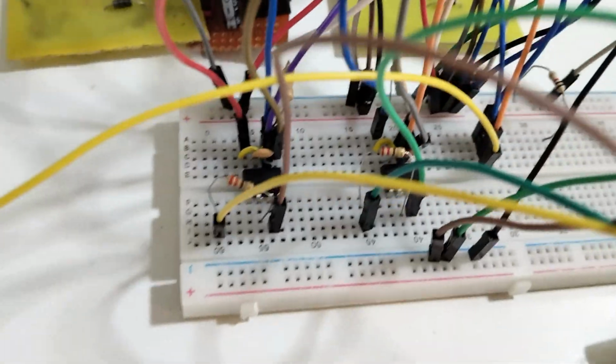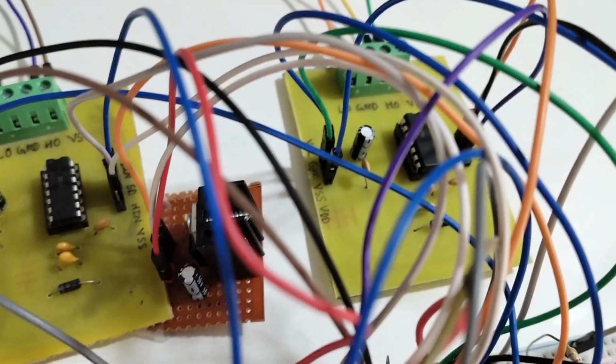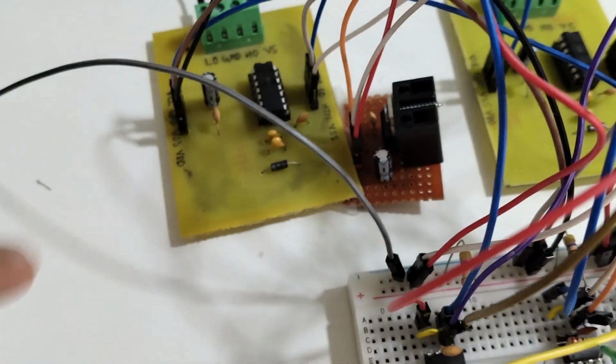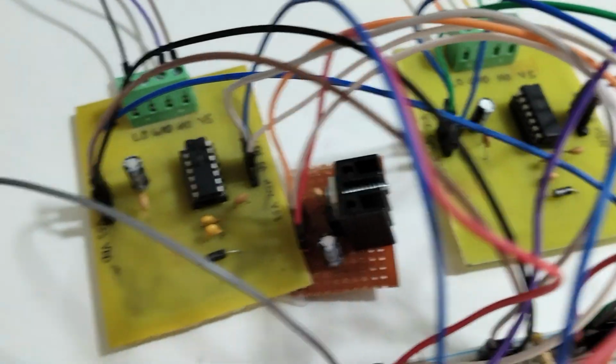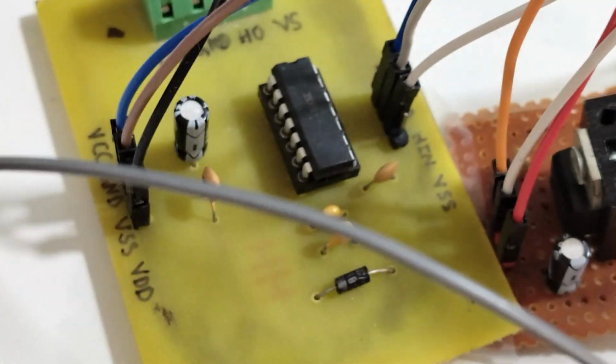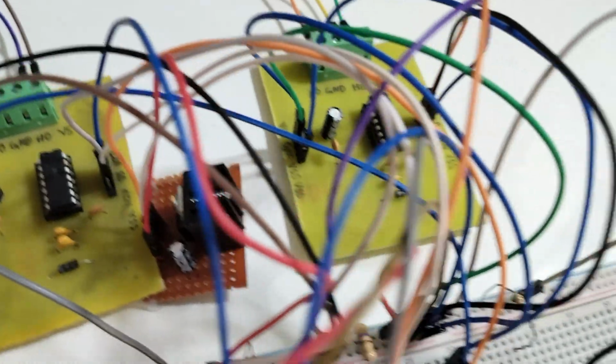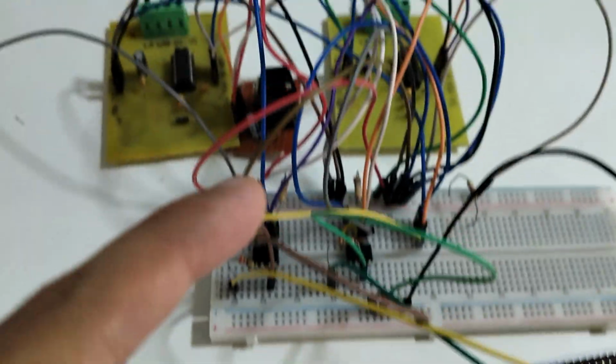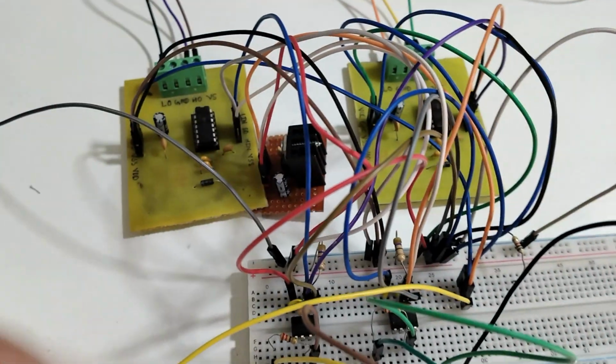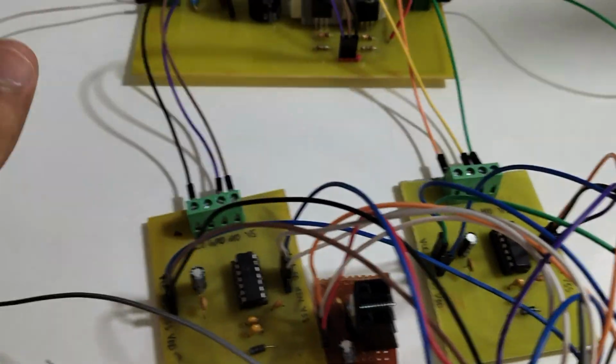So I have the two optocouplers, and after that we have the gate drivers. We need two, since we are driving two half bridges, so we need two half bridge drivers. It's the same one, the IR2110, and the PCB is ready as before. I etched it a while back, so I have two of them. They go from these optocouplers to this, and after that, this PCB is new.